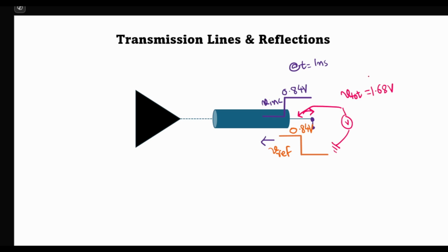So how can this happen? This we'll learn in an upcoming lecture. This is because the transmission line can be approximated by LC resonant banks, and it is the internal resonance of this LC circuit that causes the output voltage to become greater than the voltage that is launched into the transmission line. So let's now go to SPICE and visualize this output voltage with a simulation.